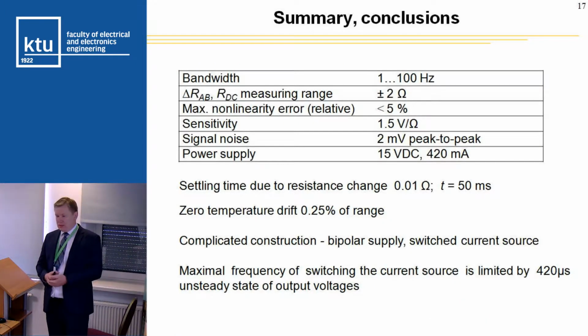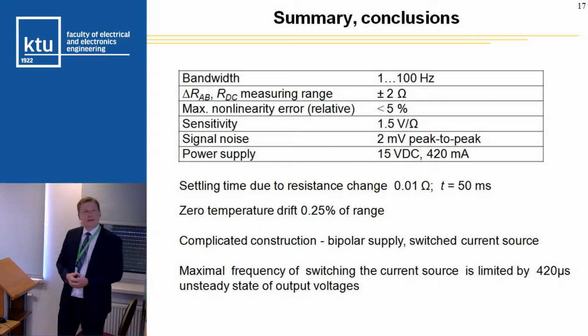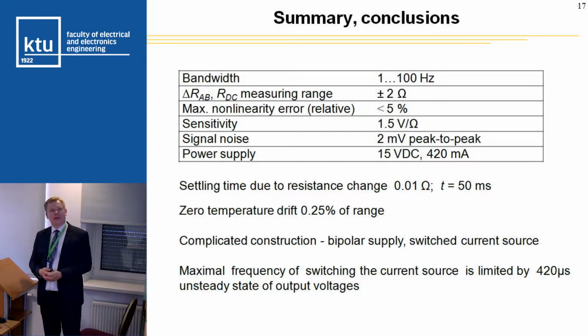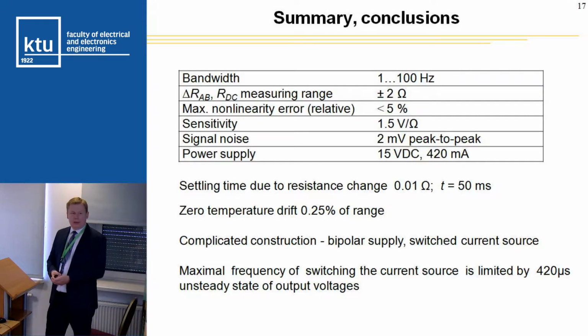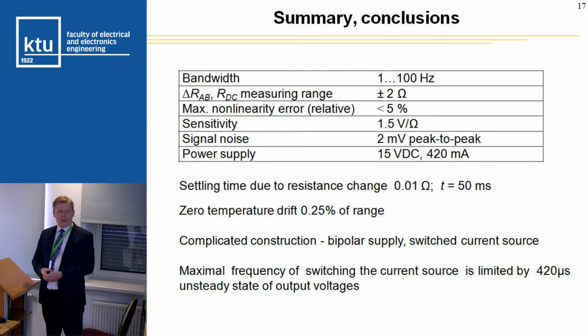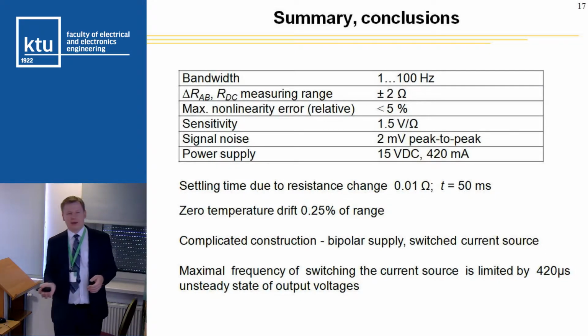To summarize this all, in this table you can see the parameters of this transducer. We also checked settling time during two resistance change, 1.01 ohm. It was 15 milliseconds. What I can say, it is quite complicated construction, because we have here bipolar supply, this switched current source.